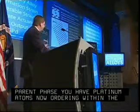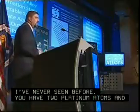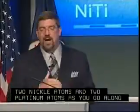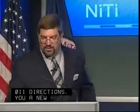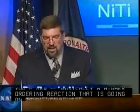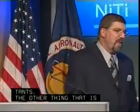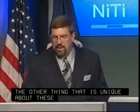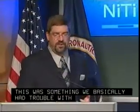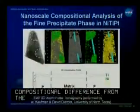You actually have 2 platinum atoms, then 2 nickel atoms, then 2 platinum atoms as you go along 011 directions in that particular plane. So you have basically a higher ordering reaction that's going on in the parent phase, causing these extremely fine precipitates. The other thing that's unique about these precipitates, if I could have the next slide, and this was something that we basically had trouble with initially, is that the precipitates themselves didn't have that much of a compositional difference from the matrix. But now that you understand this higher ordering reaction, we kind of understand that.